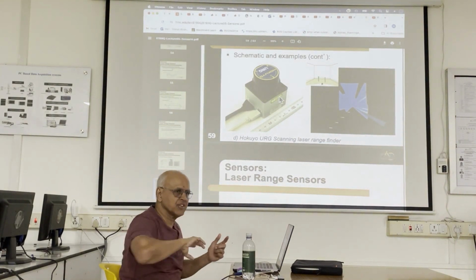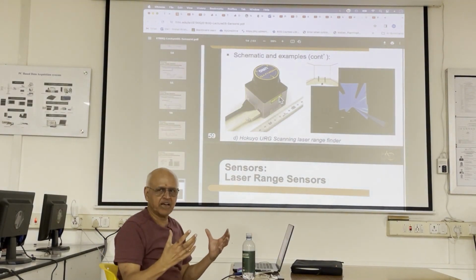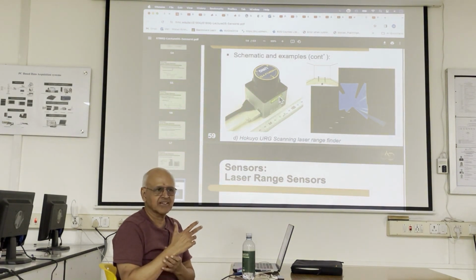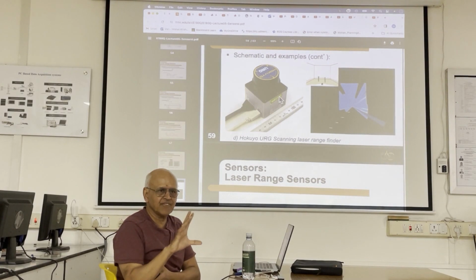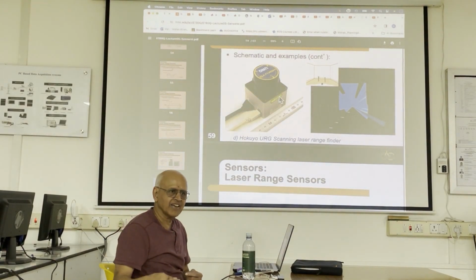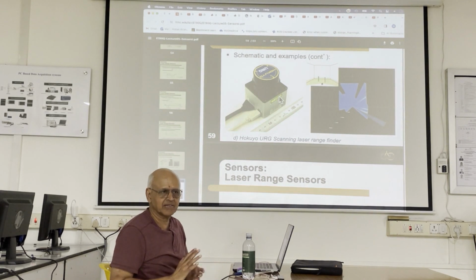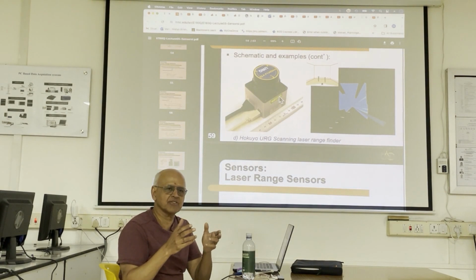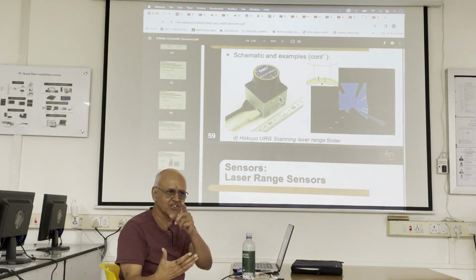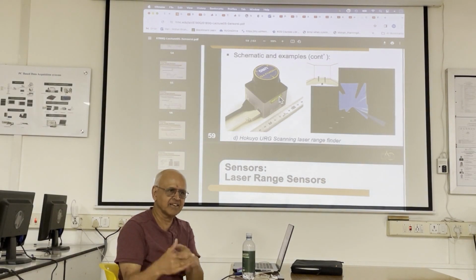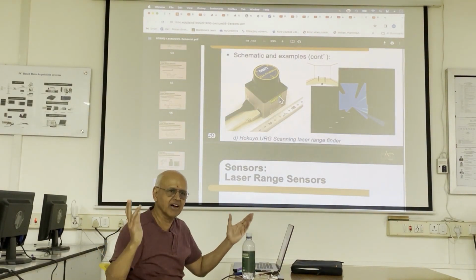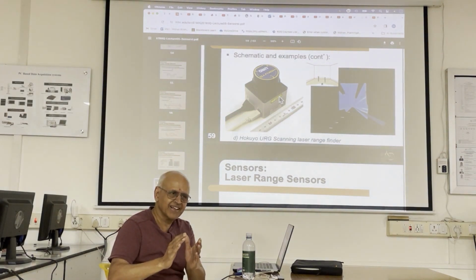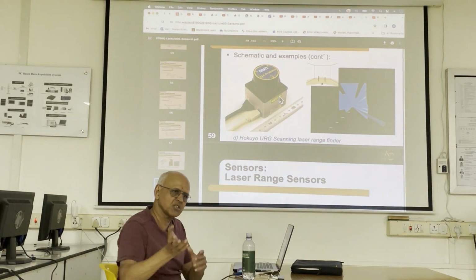So the frame rate applies to all the sensors, right? What frame rate am I getting? For self-driving cars, that has to be something like 15, 20 frames a second. Maybe it's more, but I vaguely remember it's in the tens. If you don't get that kind of frame rate, then you're going to collide. Literally it's like driving like this. And some people essentially force themselves into that mode by looking at their cell phone because they're not getting the inputs from the real scene, right? If there's nobody around and you're driving on an empty road, yeah, you can do that. Even then you'll find the car kind of veering if you don't pay attention because the road will push the tires one way or the other.